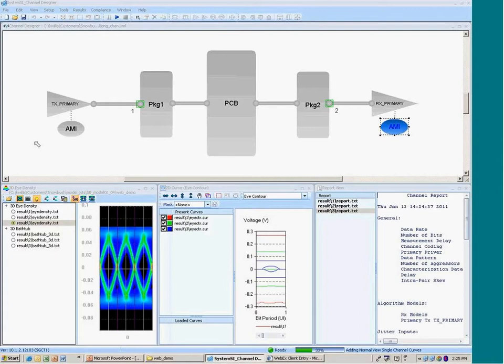So this means that if it's incorporated as part of the standard, you could theoretically have a transmitter from one IP supplier and a receiver from another IP supplier. Let's say they're both PCI Express Gen 3 components, and the goal of all of this is that that back channel capability will actually work between those two components. Eventually, it should become IP independent as this gets standardized.